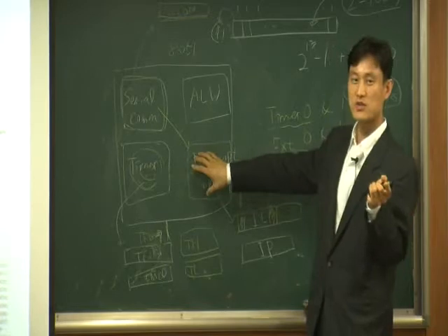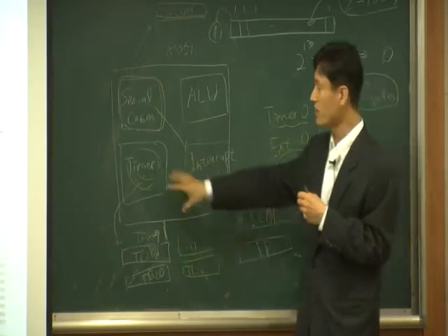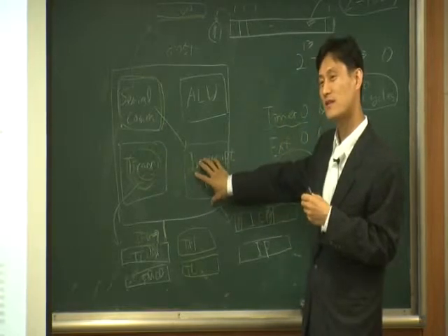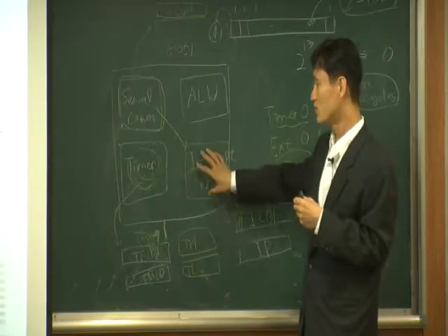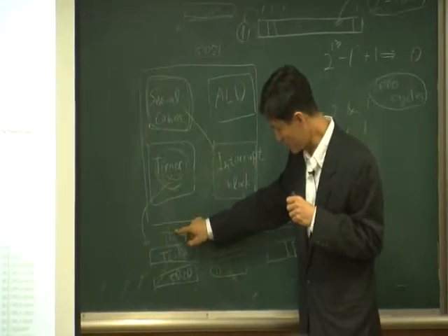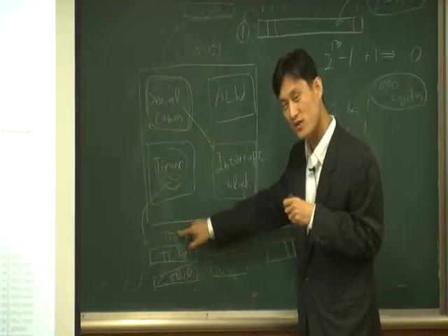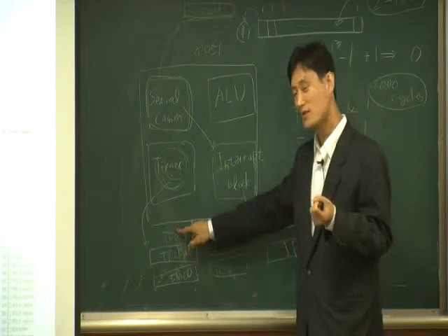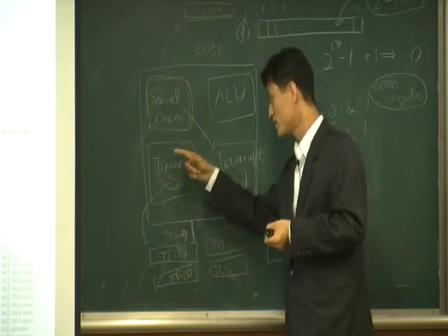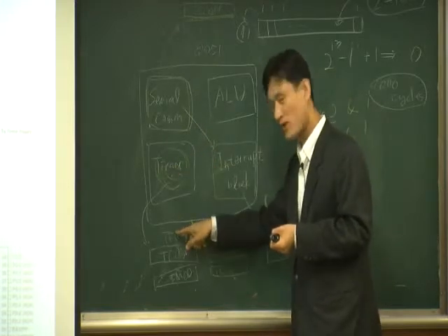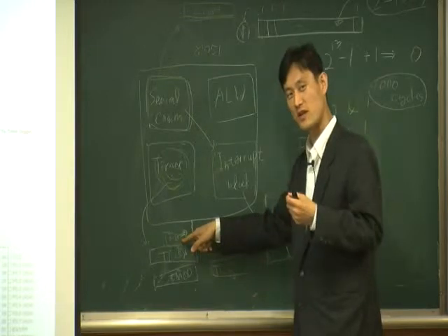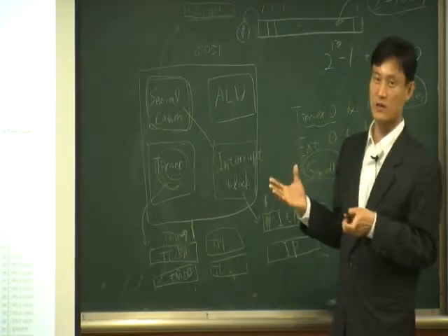In the earlier software polling, you only program this timer and you didn't use interrupt. That's why you have to watch this TF0 until it becomes 1. Because I don't know when this becomes 1, so I have to watch it until the hardware finishes 1 millisecond and sets this to 1. I want to detect that. That's software polling.